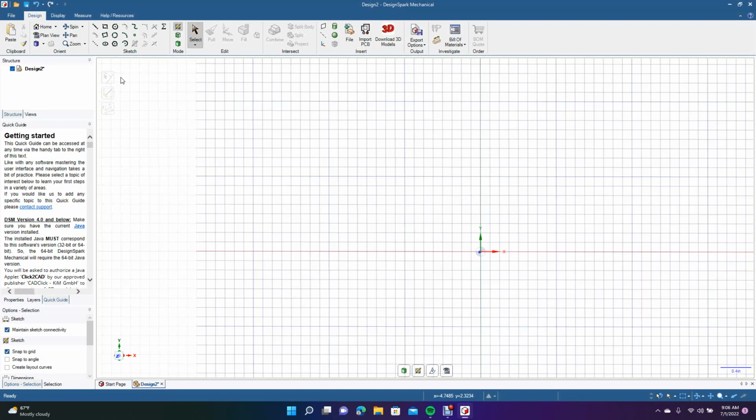Okay, so we were talking about the, I think we went over the sweep arc. Now the next tool is going to be your spline tool. Spline tool is handy to have if you want to freeform something. And I normally don't have snaps on when I do that. What you can do is go ahead and just click. Whenever you click a second point, you're able to curve.